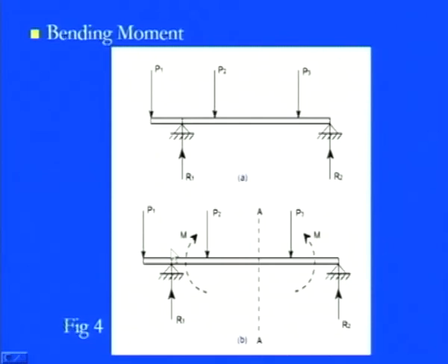If you see the real feasible situation here, what the resultant is, in terms of bending, these two forces will tend to move this beam in the downward direction. So the resultant will come towards, they are pushing in the downward direction, but the locations of these point loads are different, they are not exactly at the same position. And in between these two forces we have a point load which is acting in the upward direction. So if you now look from this AA section, from this position, you will find that the overall resultant on this beam will tend to move in this direction.